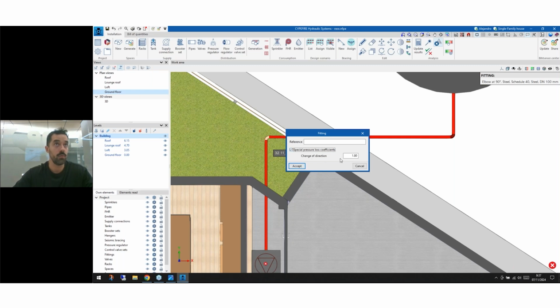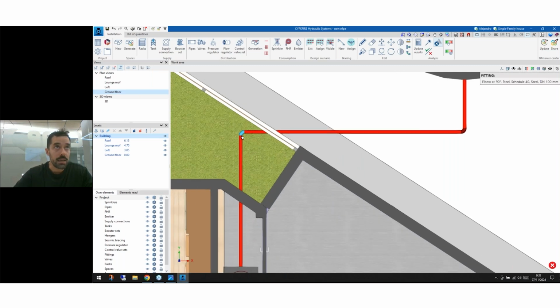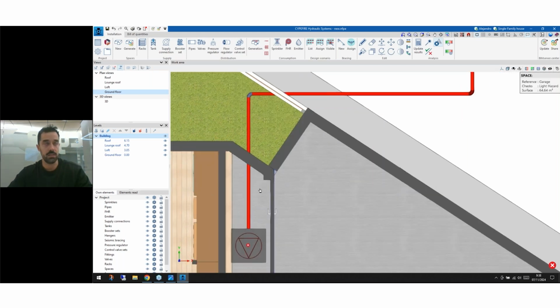Okay, if we make this and we change this to like 5 maybe, the color that this elbow has is different. Okay, and this tells you that this elbow or this accessory, whichever, has been changed manually. Okay, if we have it like this, it is done automatically, and this more gray blue is that we have changed it.